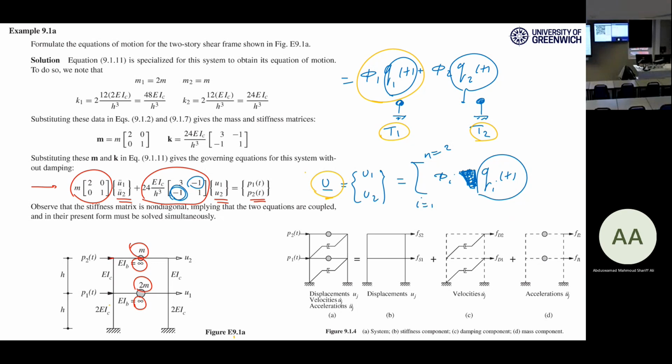T1, T2 are called natural periods, and phi1, phi2 are, or better saying, T1, T2 are eigenvalues, natural periods, because they are coming from a sort of analysis which is called eigenvalue analysis. They are eigenvalues. It's a name of the analysis. You will see how it works. Okay. And phi1 and phi2 are called eigenvectors.